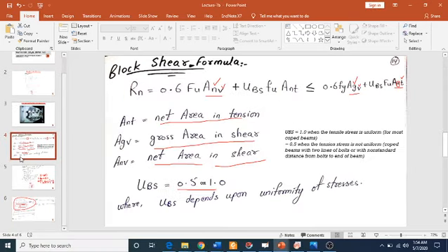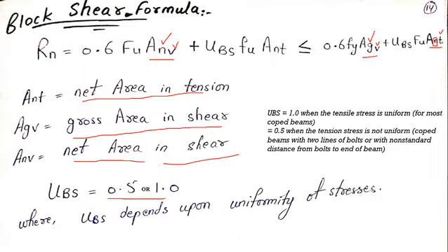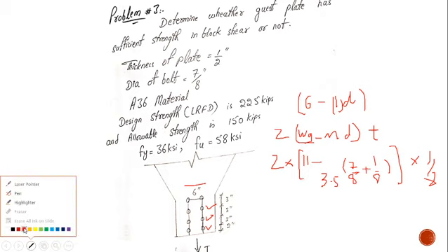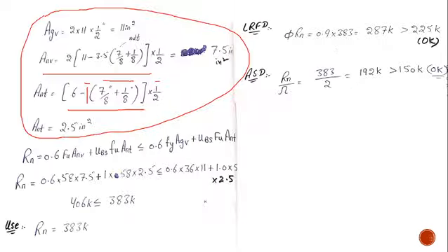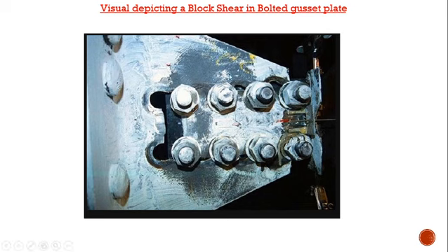N की वैल्यू 1 किस लिए भाई, बिकॉज हाफ बोल्ट ये है और हाफ होल ये। हाफ होल गिव्स यू 1 होल। तो हम यहाँ पे भी देख सकते हैं। आपको समझ आना चाहिए। ये देखिएगा टेंशन के अंदर, इस वर्टिकल टेंसाइल रीजन में भी आप देख सकते हैं कि हाफ बोल्ट अभी भी इंटैक्ट है और हाफ बोल्ट इधर अभी भी इंटैक्ट है। इसका मतलब है कि हाफ में फेलियर हुआ है और हाफ इंटैक्ट है। इसका मतलब हाफ गिव्स यू 1। तो ये बड़ा आसान है.